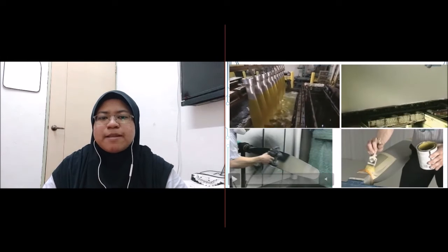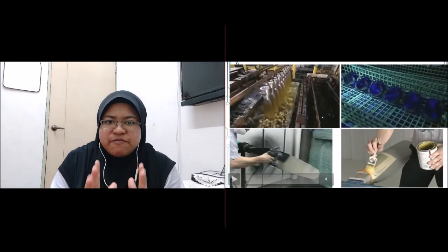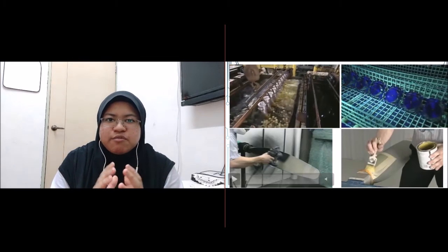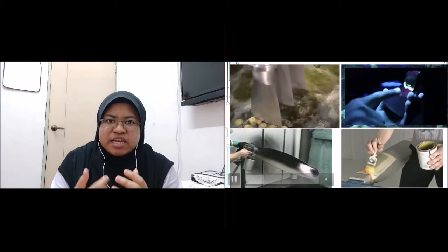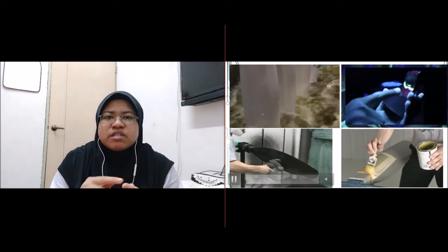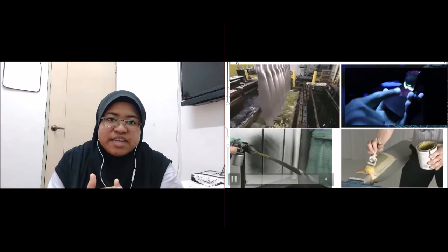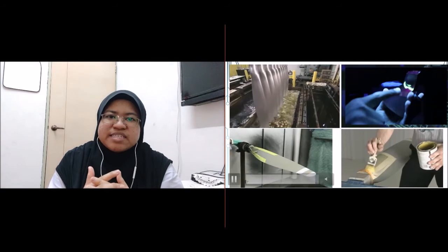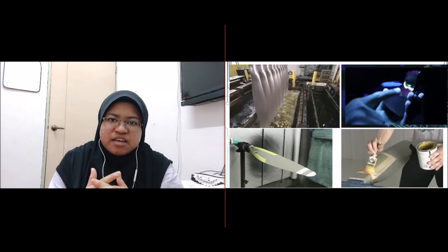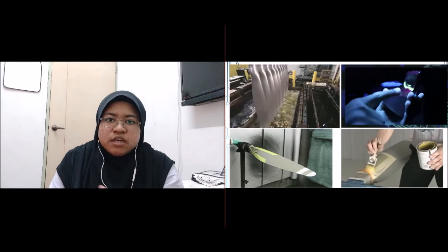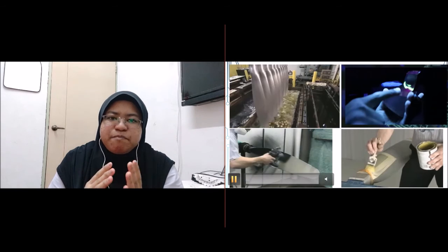A blue glow means the parts do not have any surface defects. Meanwhile, a bright fluorescent green will be shown on the defective surface. The defective parts are either repaired or rejected from the production line. Next, the blades with no surface defects that pass the factory check will be sent to the paint shop. A coat of black color on the blade back will prevent the sun reflecting into the pilot's eyes.